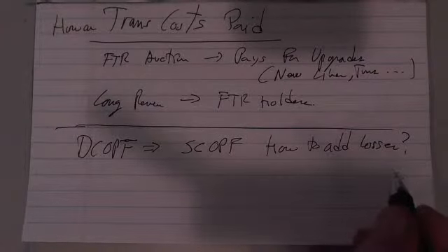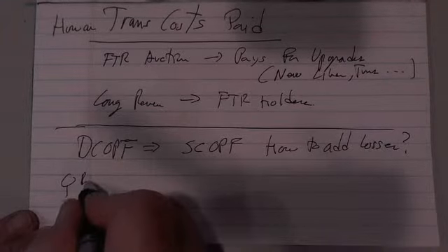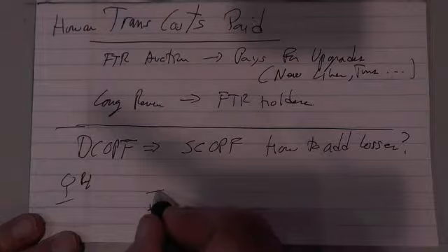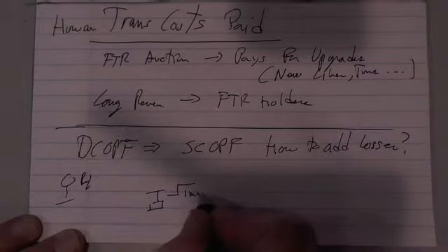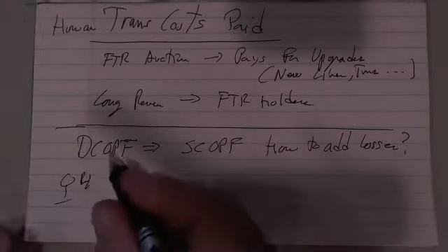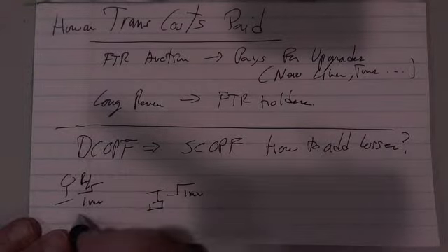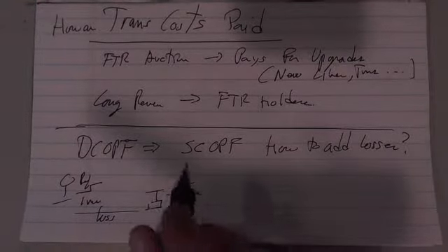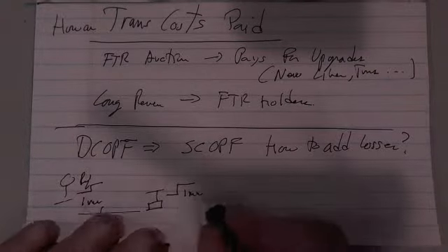And what he says is that loss factors are introduced at each node into the model formulation. The loss factor is the change in total system loss. So what they do is they say, here's a reference bus, here's a generator, and here's a load, and I'm going to go up 1 megawatt at the bus and withdraw 1 megawatt from here. Well, there's a loss component in here between the two. The loss factors are nonlinear, calculated based on the AC system model. That's right. They're recalculated, and so they develop a loss component.